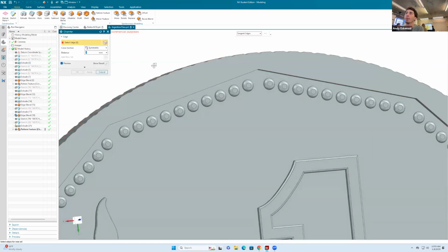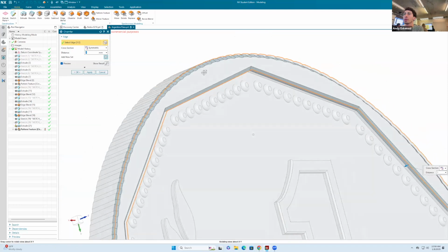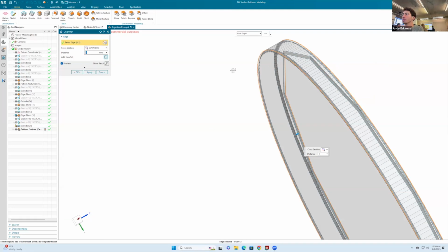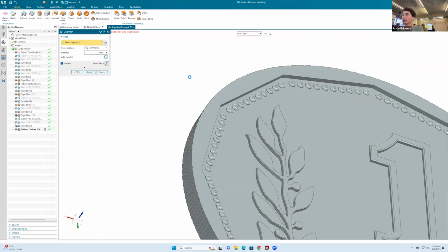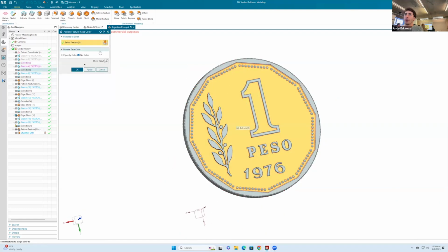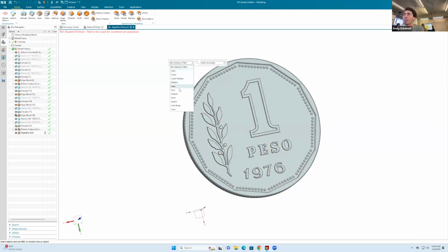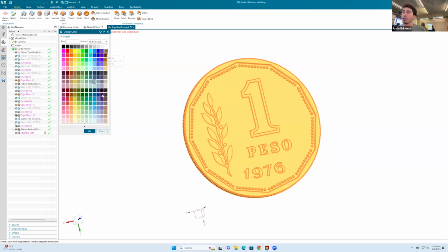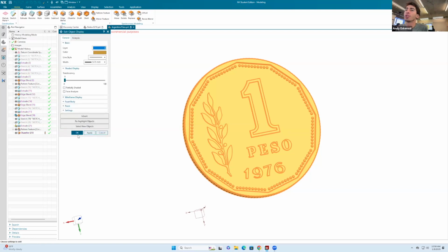Perhaps the last thing that we could do is just chamfer. Oh, why not do it down there as well? And let's assign a feature color. Actually, you can do in here it says no selection filter. It allows you to do solid body, and now this one is a command that I learned recently. Control J, and now you can just change the color of the entire body instead of doing individual features. And we can make maybe the color like maybe this brownish. I'll say okay.